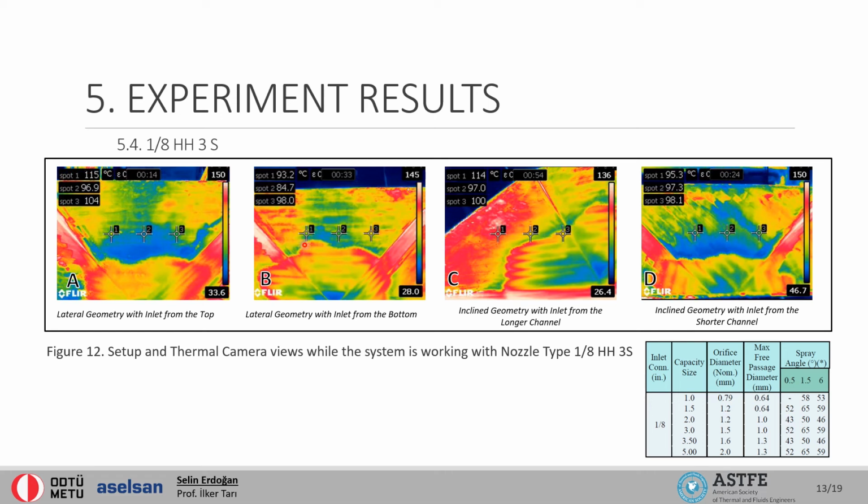So with this nozzle, we expect a greater altitude of the fluid boundary. As we can observe it for all channel configurations, we can conclude that this might be caused by a problem like a blockage in the nozzle. And when images A and B are compared, it seems like one side gets sprayed fluid with a higher angle, this side, and this might again be caused by blockage or misplacement of this nozzle. So there might be an experimental error with this nozzle.